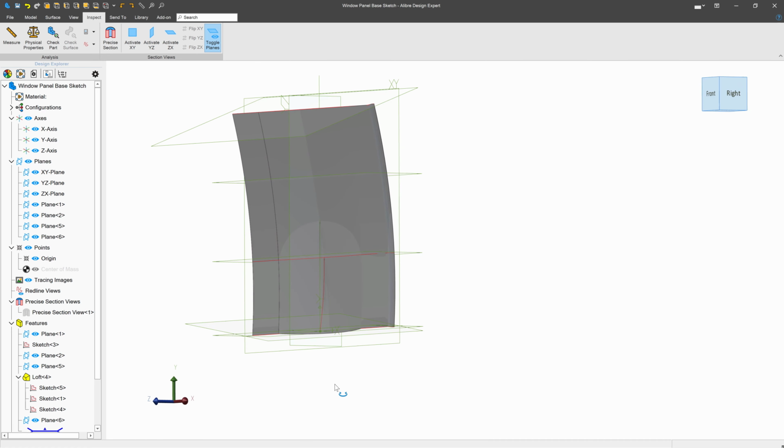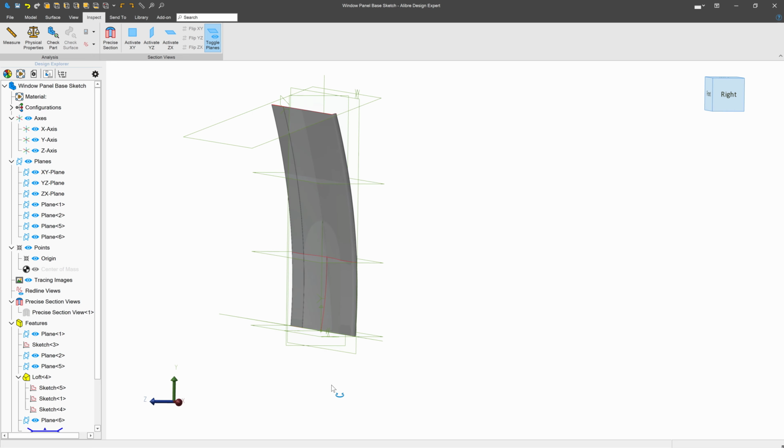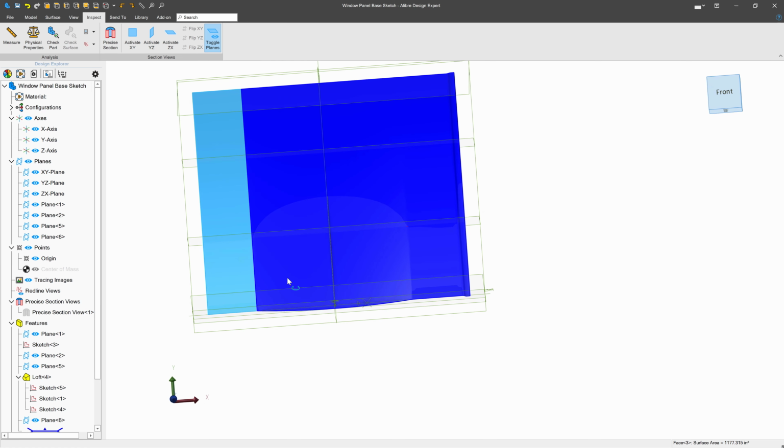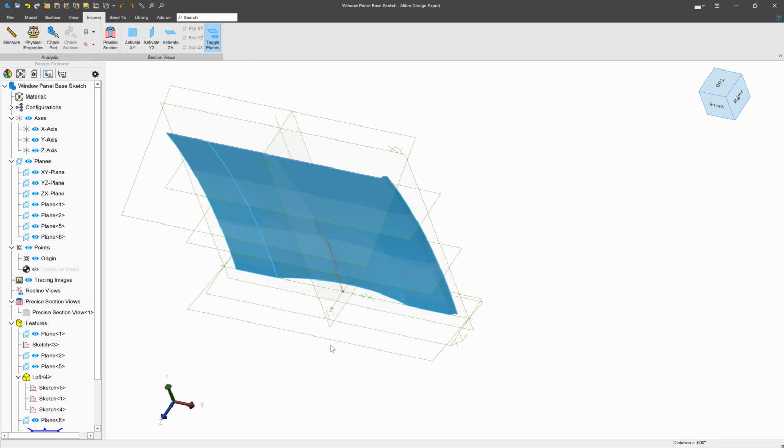Instead of worrying about having a constant thickness in all of my sketch profiles, let's just worry about getting one face. And I'm going to choose this inside face. If I can get this inside section correct, then let's say I am good to go. It sure is a whole lot easier just thinking about one face instead of the entire part. So, in order to achieve that, I can simplify everything else.